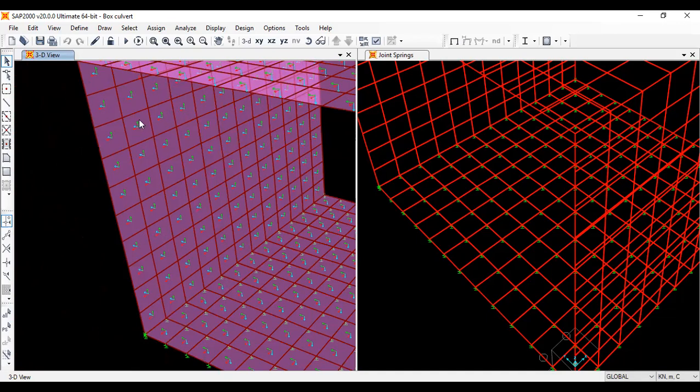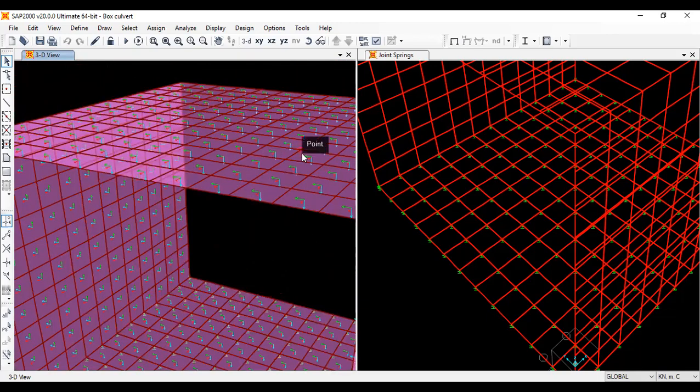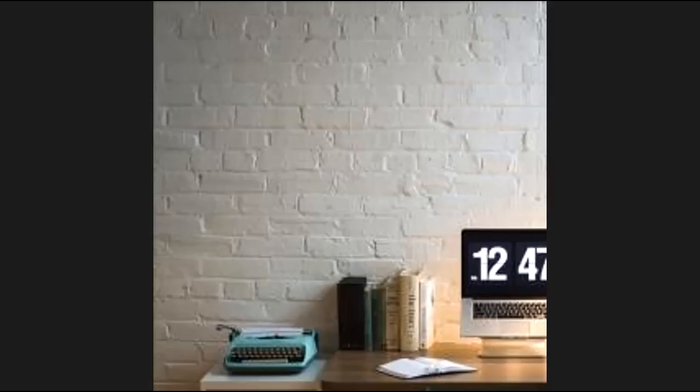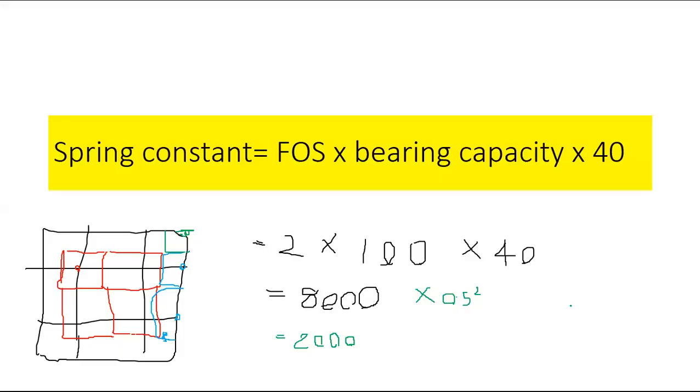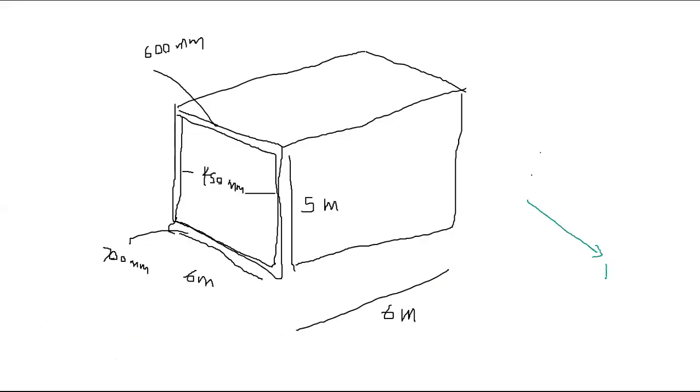So that will also be bent around. That will be given also by second direction moments, right? M22. So this also will give M22 because it's not like the beam. The bending is defined by like this. I'll show you. If you have axis 1 and axis 2 for this shell element, the bending 1 is like this, and bending 2 is like this, right? So actually the bending M22, this is M22.